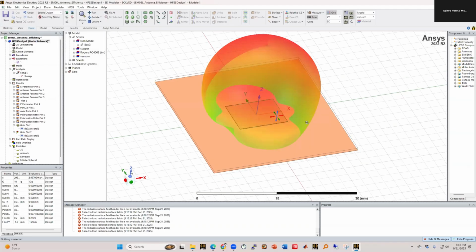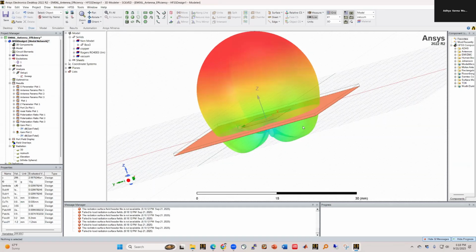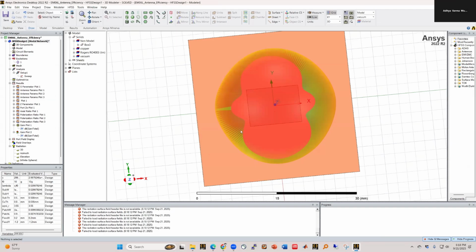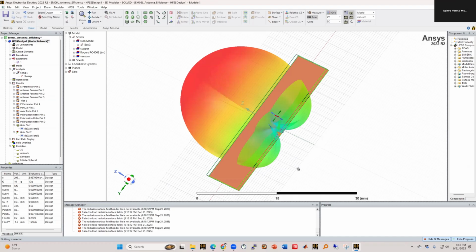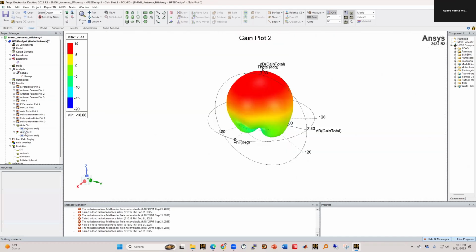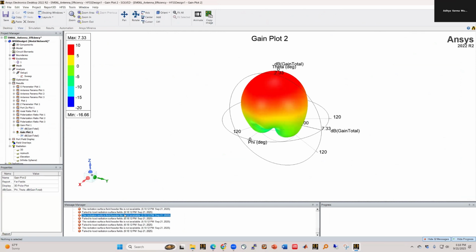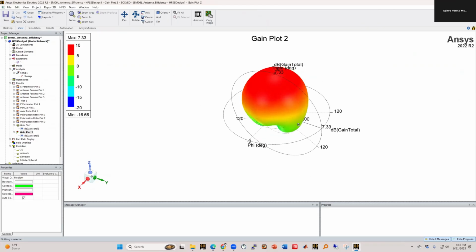Okay, so this is showing us that in the E-plane, which is this plane, there are these two lobes, right? And in the H-plane, which is this plane, those lobes don't show up, right? So really you have a 3D radiation pattern, but you're only plotting it in two cuts here. And that's usually good enough to represent what the beam pattern may look like, right?